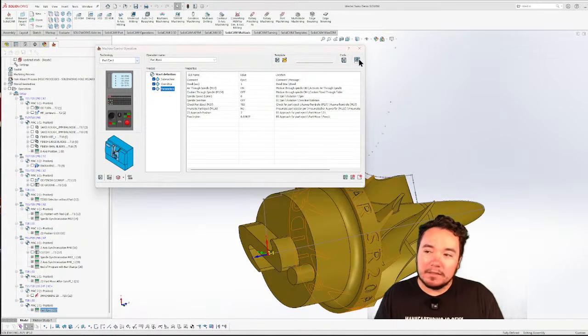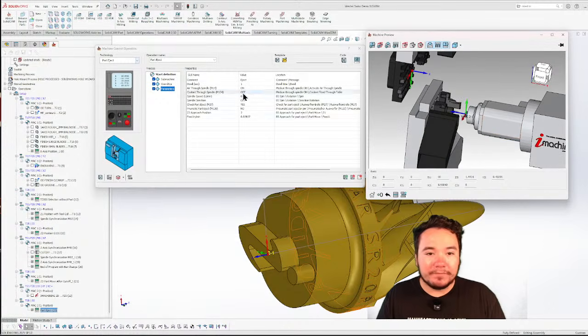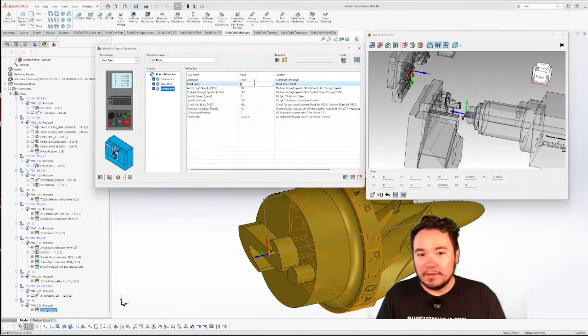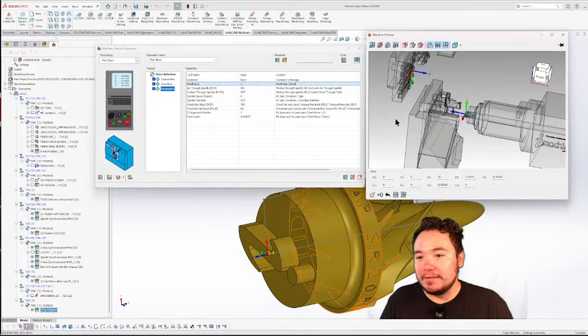And when I did add the part eject, one thing that you do have to add is you can add a dwell in there. It's in seconds. You can do longer, however you'd like to put it. Air through spindle, I turned it on, yes, as well. For this specific one, there's a plunger, a spring-loaded plunger, so the second that there's no pressure in there up against it, it'll just shoot it right out.